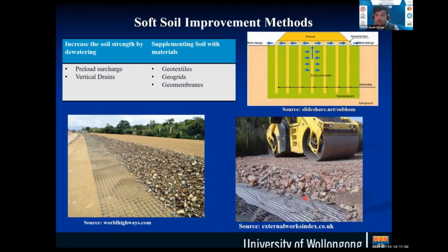During this whole process, what practicing engineers often observe is that these geogrids get caught in this machine and it becomes a very big issue during maintenance. We have observed some reported cases where the geogrid has to be completely removed for the realignment of the road, and in turn it becomes additional waste as part of the construction process.